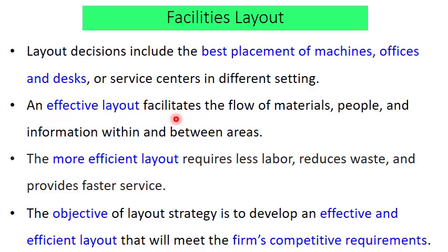An effective layout, by the way, facilitates the flow of materials. Not only the flow of materials, but also the flow of people and information within and between the areas of the firm. So an effective layout increases the speed of material, people, and information flow within the compound. The more efficient layout requires less labor. This is an advantage in reducing the cost.